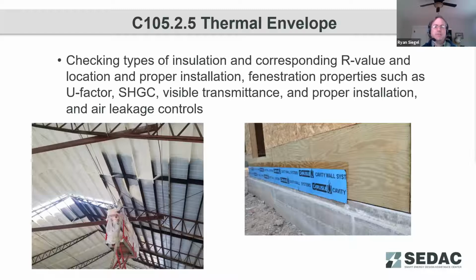In this one example here, they require the wood to be primed before application of this sealing tape, and then they would probably require that it be rolled afterwards. So again, making sure that that is going to adhere well to that substrate. Definitely don't want to see peel and stick membranes becoming stick and peel membranes.